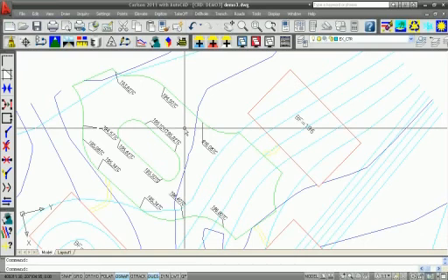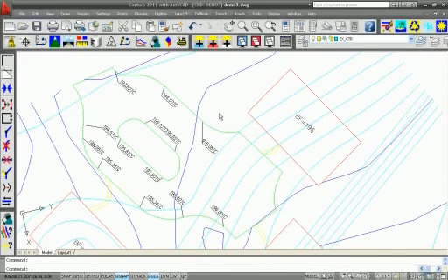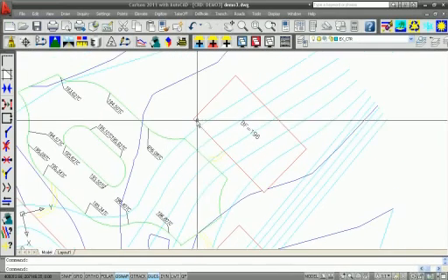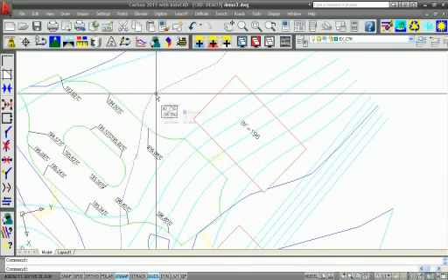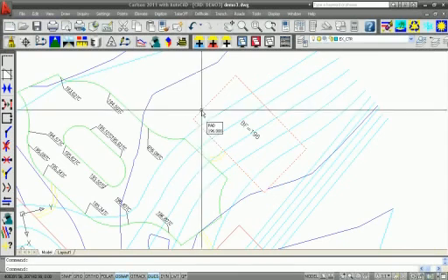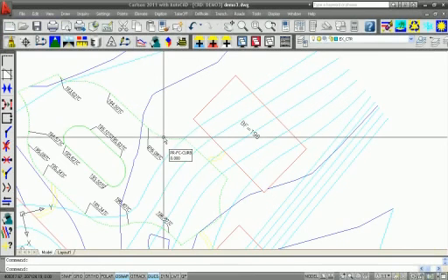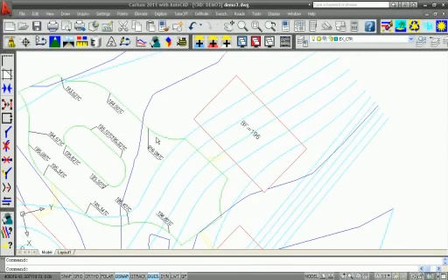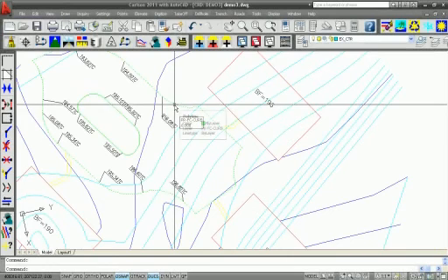Thank you, John. If you have the time to stay with us, I have about 15 more minutes of some features to show, for elevating line work on a contour line like this. So you can see I have some elevated line work in here. The contour line's at 196. This is pads at 196, and this curb line is at 0 elevation.